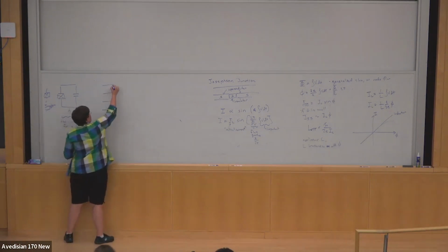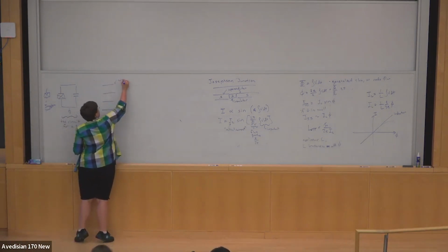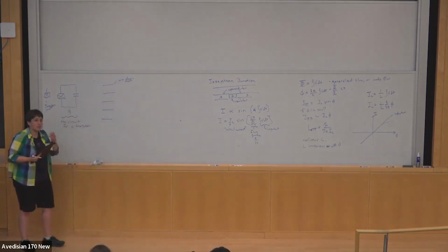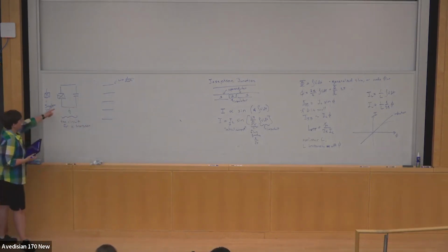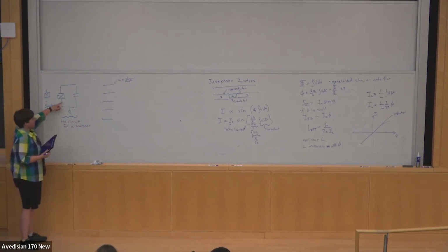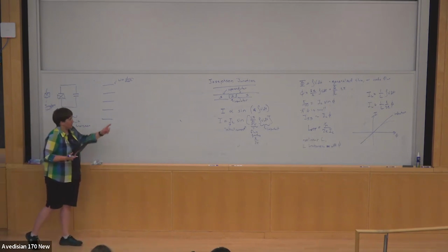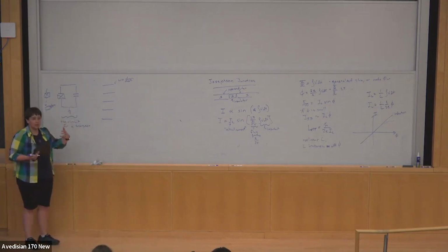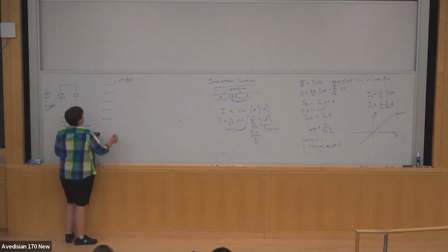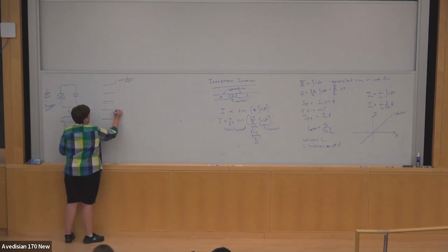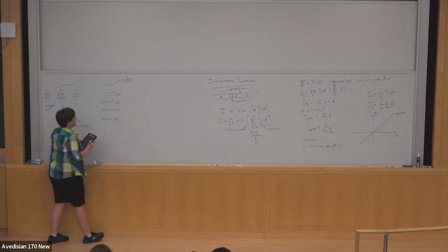And so these are the levels for just a basic harmonic oscillator with the same effective inductance as the superconducting qubit. But as you go to higher and higher excitation, you see that the junction is nonlinear, and it looks like it, in fact, has a higher inductance. And so what you see is that the true states of the transmon look like this.